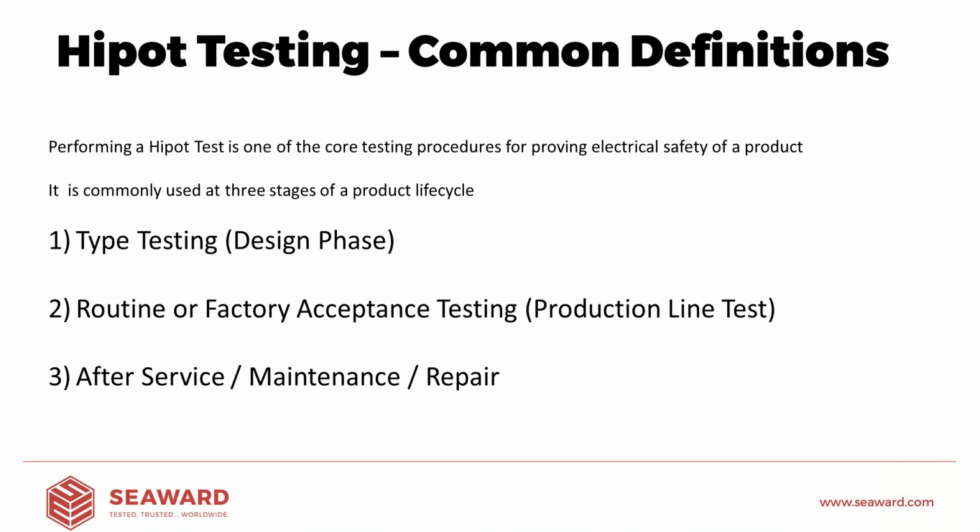We know that. What we're now concerned with is, has somebody or has the act of building it potentially made it weaker? Potentially somebody's overscrewed a screw and they've managed to pinch one of the live cables or something along those lines, or we've trapped the cable within 2 parts of the chassis, and then when we turn the power on, it potentially becomes live.